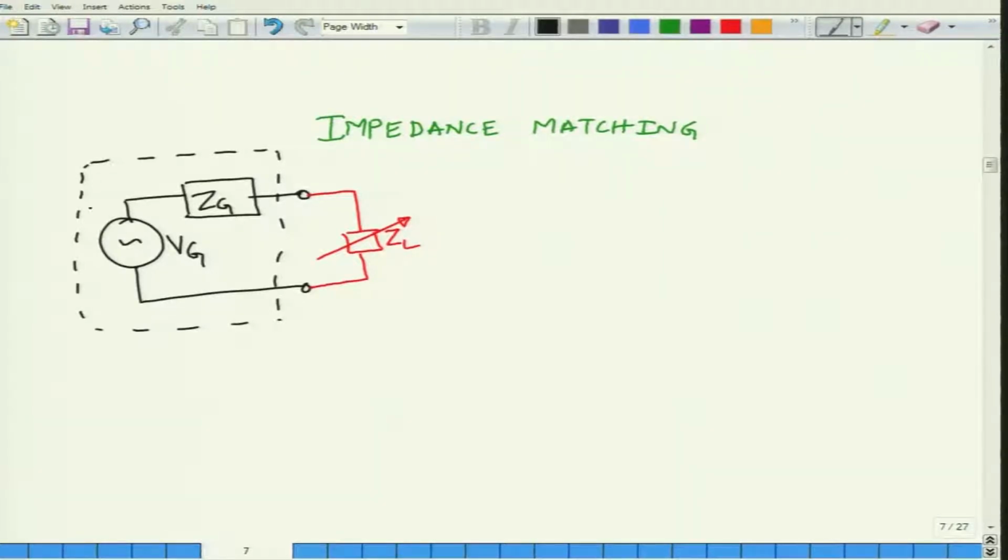That is why it is called an internal impedance, and this is idealized by the fact that we have drawn dashed lines around this source. So, this is not a perfect or ideal source, this is an imperfect or practical source, which has an impedance Zg internal to it. Let us also assume that the source amplitude is some Vg. In the discussions over the last few modules, Vg happens to be a phasor, but for our discussion it is not really important to know the form of Vg.